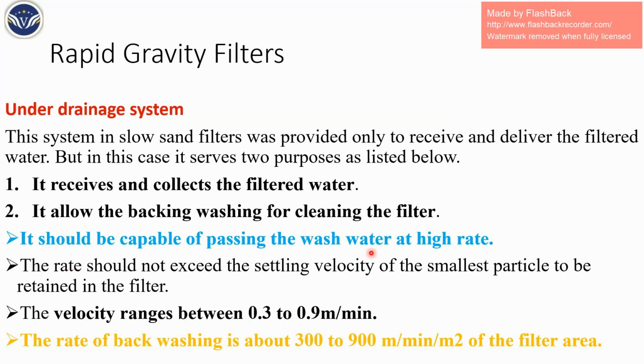It should be capable of passing back water or wash water at a very high rate, because only with a high rate can the cleaning take place. It should have a non-settling velocity. Please remember this. The velocity will range from 0.3 to 0.9 meter per minute.